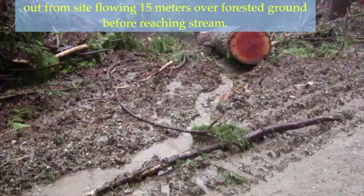meters, it will only take a couple of meters of filtration over forest floor before it's going to be completely absorbed. On the other hand, if there is 300 or 400 meters of road 6 meters wide, the amount of surface flow will be very high. It might take 100 to 150 meters of flow over forest floor before it's going to be reabsorbed. For this reason, the relief culverts of many roads located parallel to nearby streams are at least partially connected to the stream.